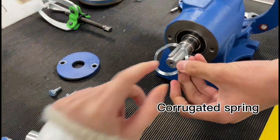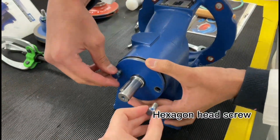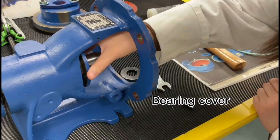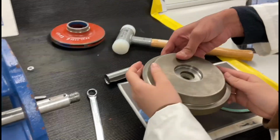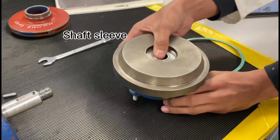Place the corrugated spring on the center of it, covered by the bearing cover, then screw it with head screw and do the same thing for the other side. Put on the splash ring. This whole unit is called bearing block. Then insert the shaft sleeve into the packing gland. Yes, you might need a hammer for this.